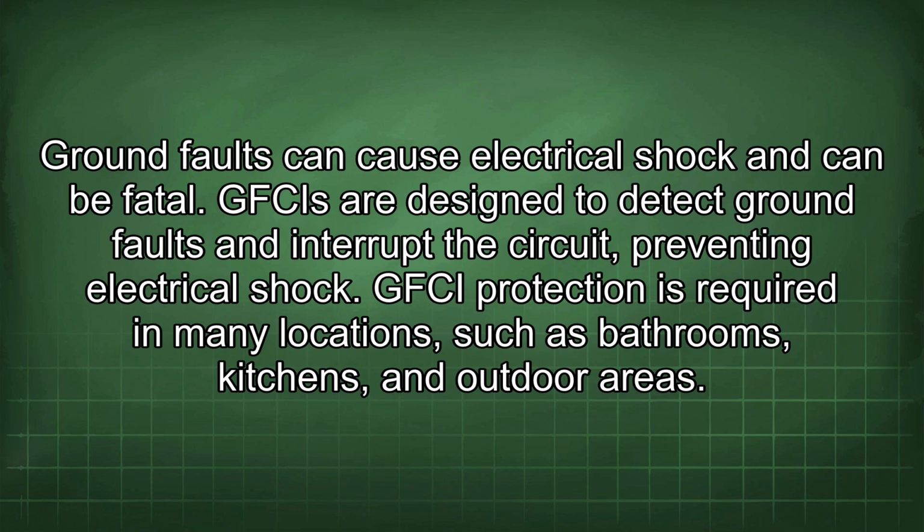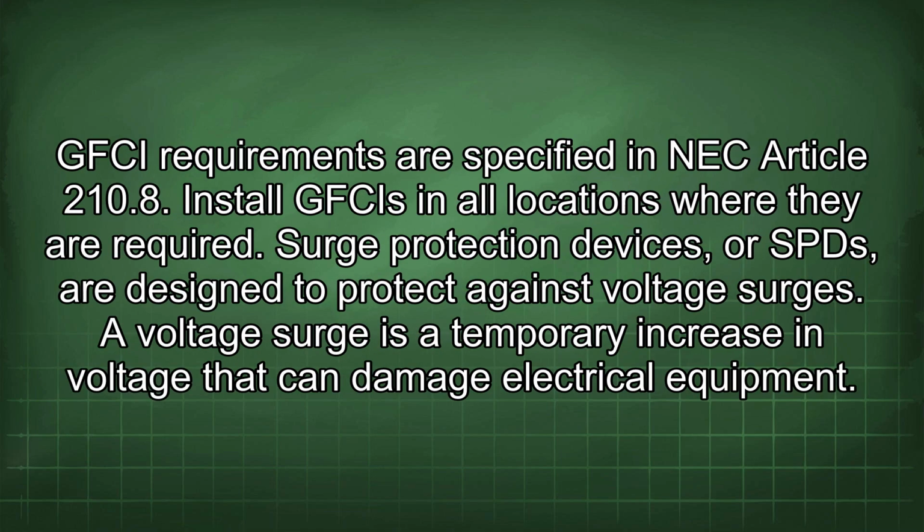GFCI protection is required in many locations, such as bathrooms, kitchens, and outdoor areas. GFCI requirements are specified in NEC Article 210.8. Install GFCIs in all locations where they are required.